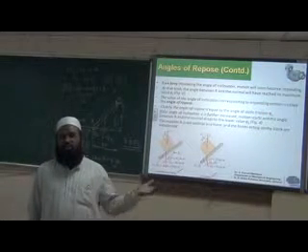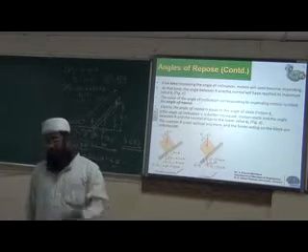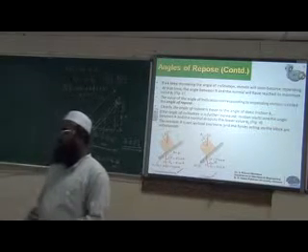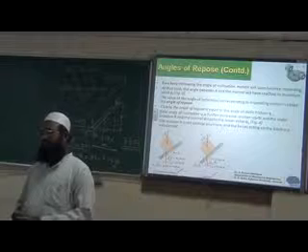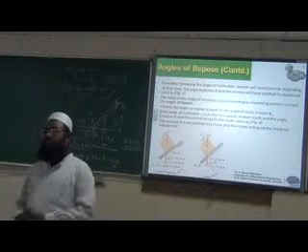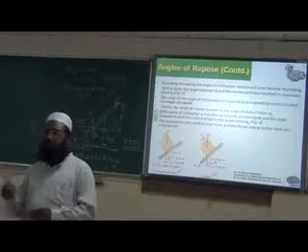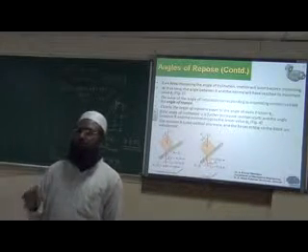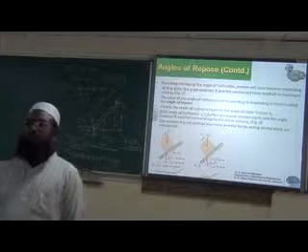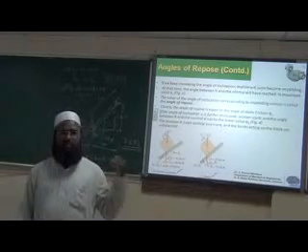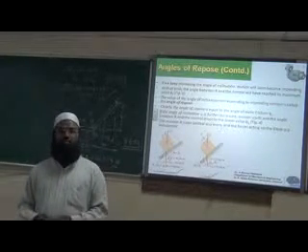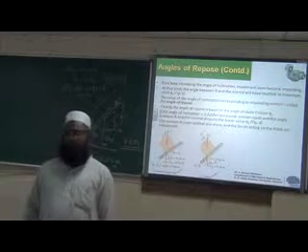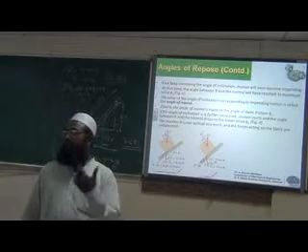So we have to consider again the same sigma Fy, the moment equation, and the same procedure. We have to find out mu. We find the frictional force Ff. The normal force we already found by the sigma Fy equation. The moment equation can be used for finding the frictional force. Then find out mu.